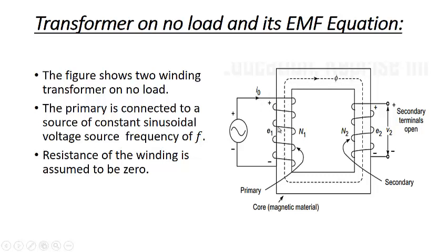Now the EMF will be induced in such a way that the current produced by this EMF will produce a flux in the downward direction, because it will try to oppose this flux and decrease it. So it will try to make flux in this direction, and in this case you have to do the reverse to calculate the direction of the current, by assuming the flux to be in the downward direction. By doing so, you will get the current direction to be opposite, like this, like this, like this, and like this. That means in this direction.